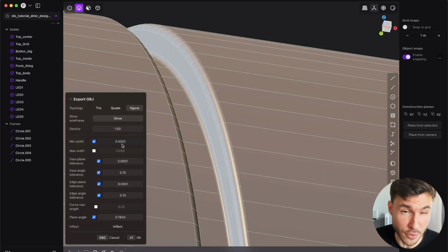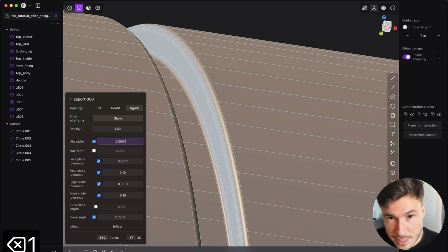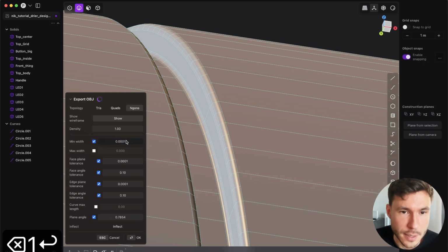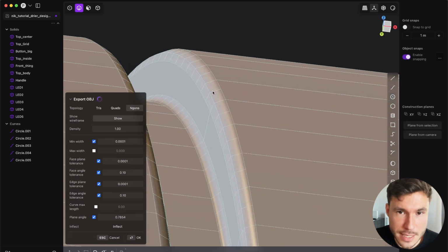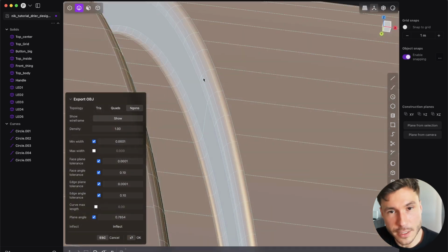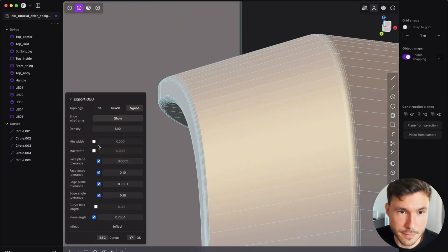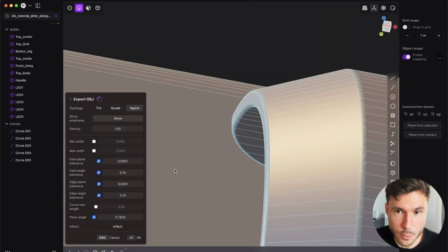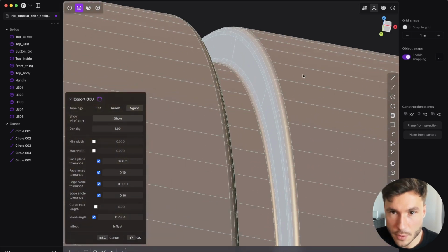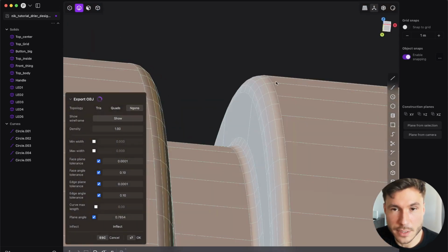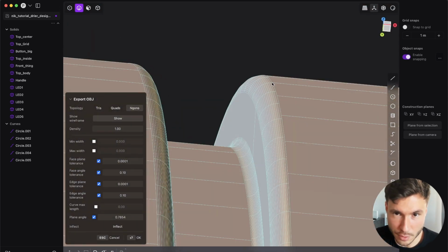We have to go to super small values, but just drag a little bit along, or just copy the values right now. If we go down with the value, now you see we have a fillet with 4 segments, and this is fine. Because if I uncheck that, as it was, those 4 segments would be like 20 or so. That's why just min width.